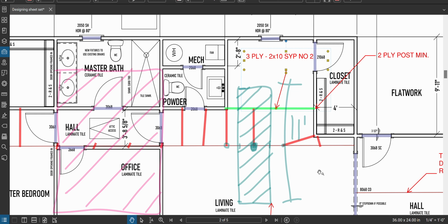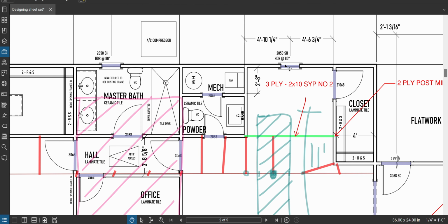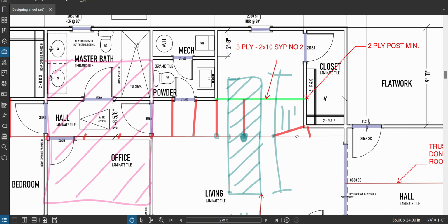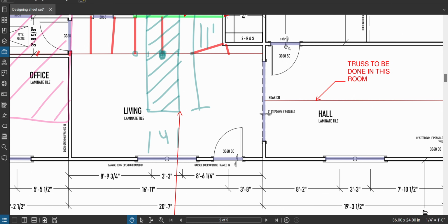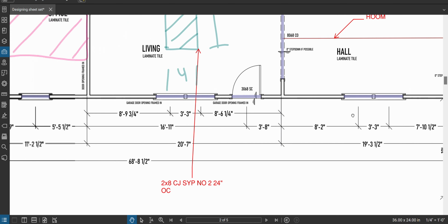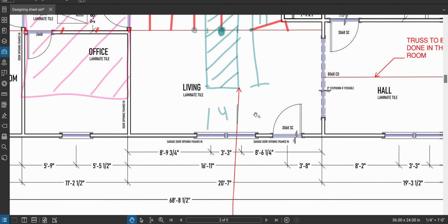In general, you'd want your exterior walls to always be a double 2x6 header, just because you're going to have more stuff going on the outside of your house. You're almost always going to have roof on it, right? So double 2x6 headers there and there. There's another one that could probably be a 2x4, nothing crazy. That one also double 2x6. This one double 2x6. Even though it's wider, like I said, it's supported in the middle, so it's okay. It's still strong enough.